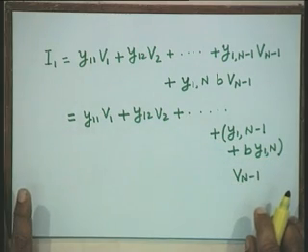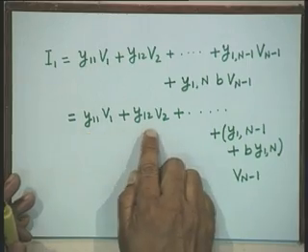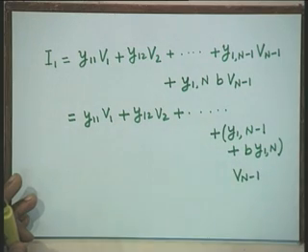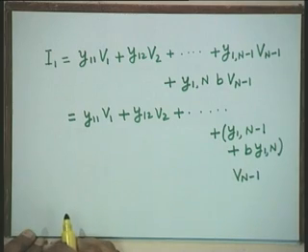Therefore, what I see here is that in the Y bus of the network, this Y bus is now going to be n minus 1 into n minus 1, and the last column is going to be different. Otherwise, y 1 1, y 1 2, these elements up to y 1 n minus 2 will be the same. Okay. Now, similarly you can write down for all the buses.